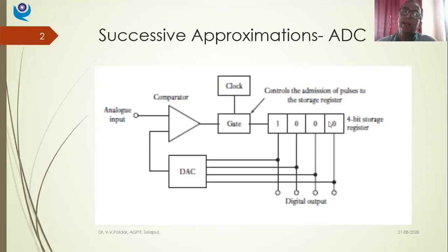Now this digital 4-bit number will be given to my D2A converter. So that D2A converter will convert my digital signal corresponding to 7.5 volts into an analog signal. Understanding it? I'll repeat it. Just be attentive. I'm not taking any signal from the transducer presently. I'm taking signal only from my clock, whose frequency and whose amplitude I can adjust.